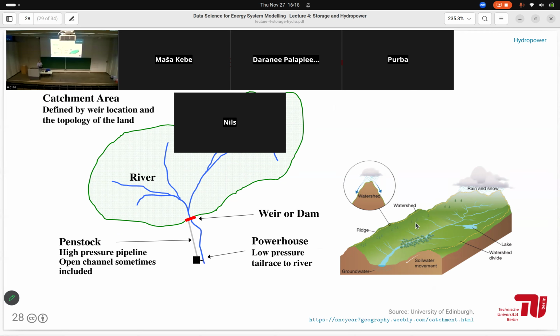So an input data set that we would use for this is a data set that lets us know about the elevation, because then we can compare, for example, in a rastered data set, the height differences between neighboring pixels and calculate in which direction we would see the flow. So one assumption you could make, for example, is that the water would flow in the direction of the steepest descent.